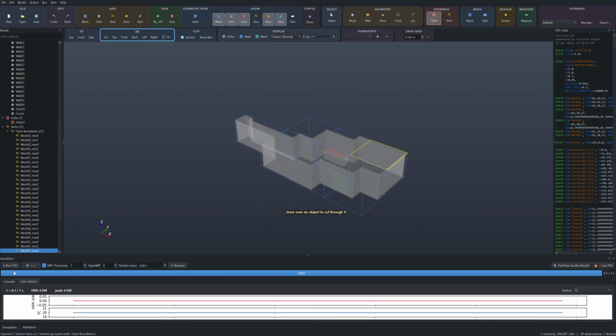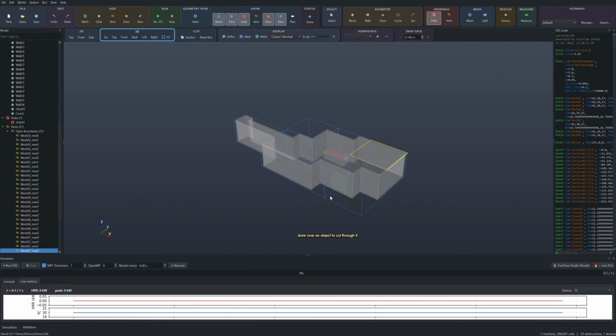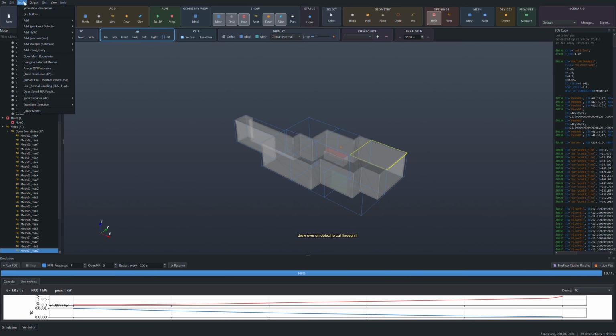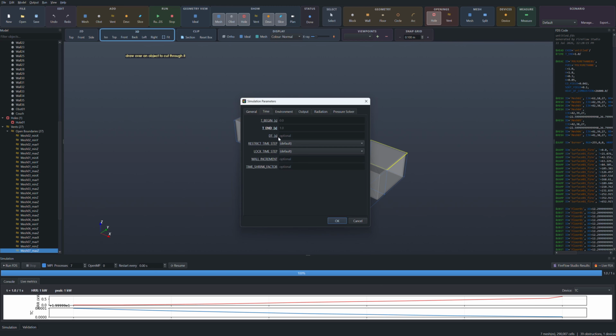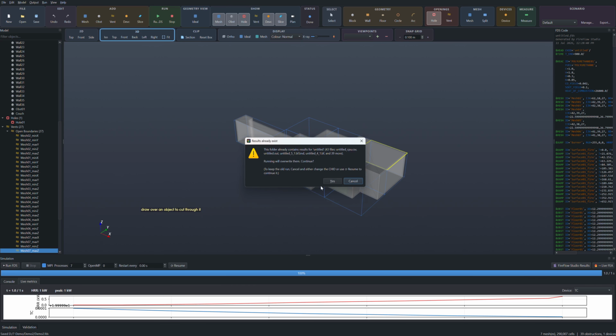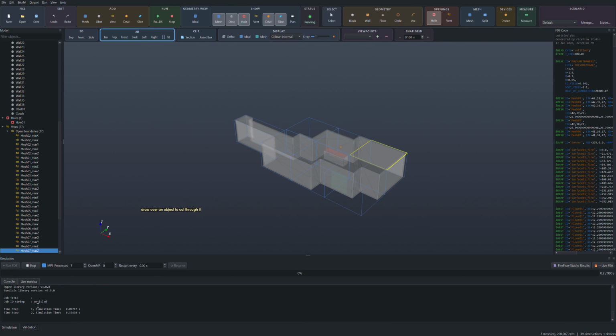So now, if I say run, it's going to tell me that I already have saved files in there. Let's overwrite it. It's going to pick up how many processes I have. And again, it's good that we're going through this because there's a few things that come up. We have not actually set our model parameters. So let's just increase our model time to 900 just for demonstration purposes. And I'm going to run again. Yes, it automatically picks up 7 processes. It's going to split those automatically.